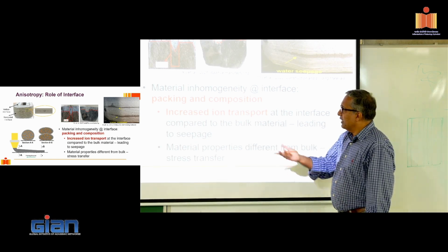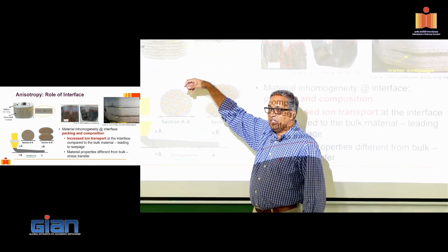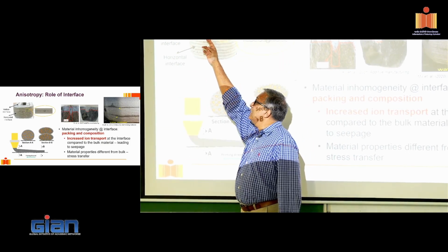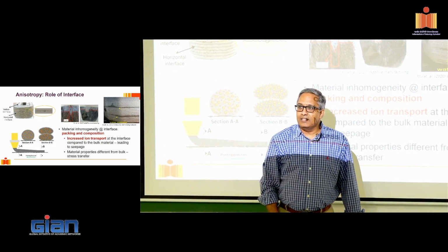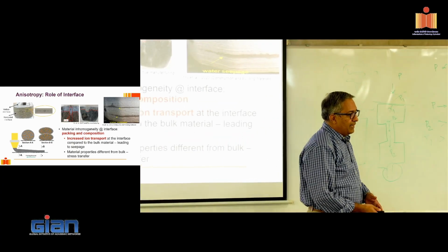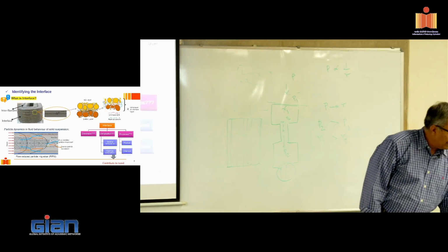Now, what do I have here? I have a chain where I have multiple filaments that are connected by the interfaces. So if I was to pull on this, what would happen? Basically, the strength of the weakest interface would determine the strength of the entire composite. Right? So these are the complications that we have to deal with when we're talking about the interfaces.